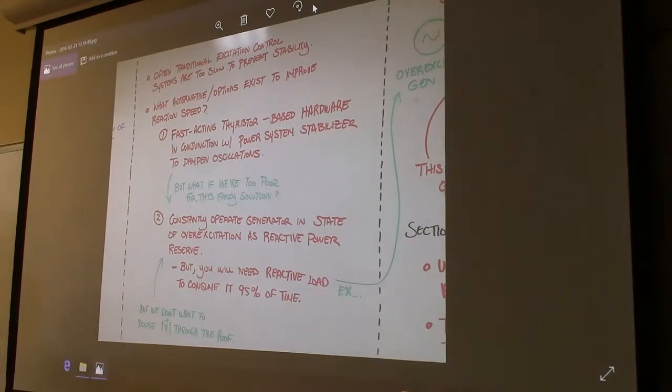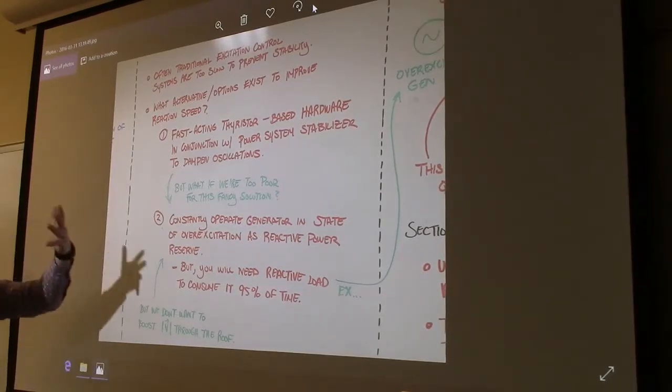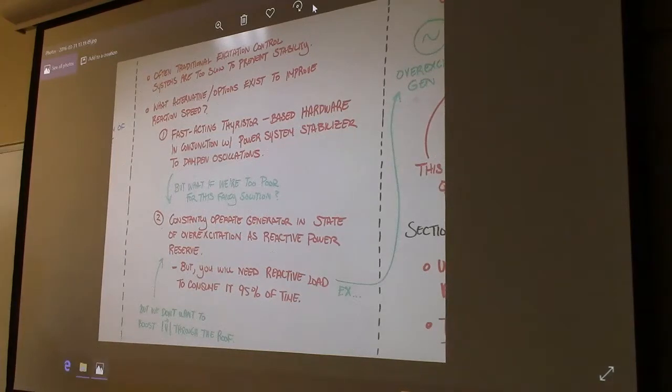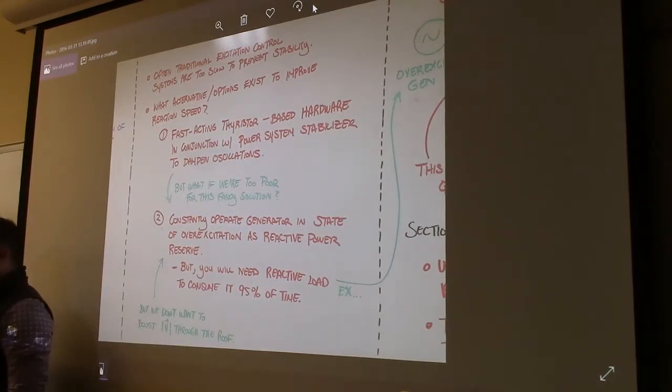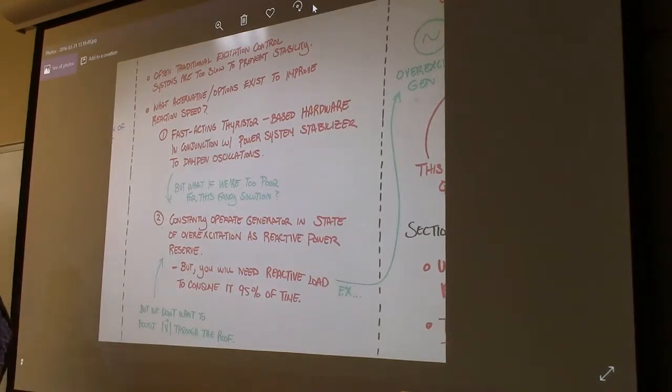And it's hotter than one might think, so the AC uses more power, and more people are turning on their air conditioning. So that would be an example of a slow movement towards instability. And in that case, you could use the generator excitation control system to overcome that. It would not be very helpful in the case of lightning striking a line or some sort of very sudden outage or something like that.